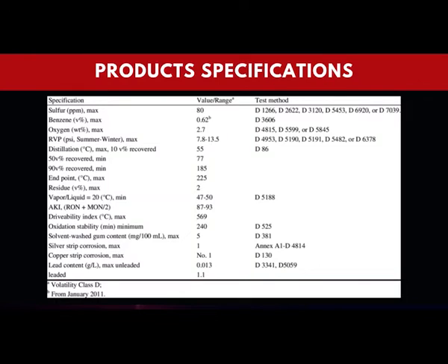For every product we have a specification. The specifications have specific values and engineering units, with a minimum and maximum cap, and each of these tests signifies certain functionality of the product. For example, certain properties denote how the product needs to be handled. Flash point is very essential to know how the product can be safely handled and stored. The octane number of gasoline is important to know whether the engine is going to have some knocking or not.